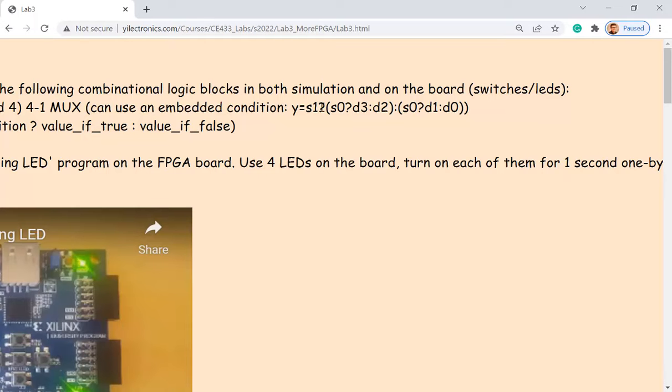So it's a question mark and colon. So the colon separates the 2 options. And the colon is making a conditional statement work. So it's asking if S1 is 1. If S1 is 1, pick up the first one, the left side of the colon. If S1 is 0, select the second one, the right-hand side of the colon.